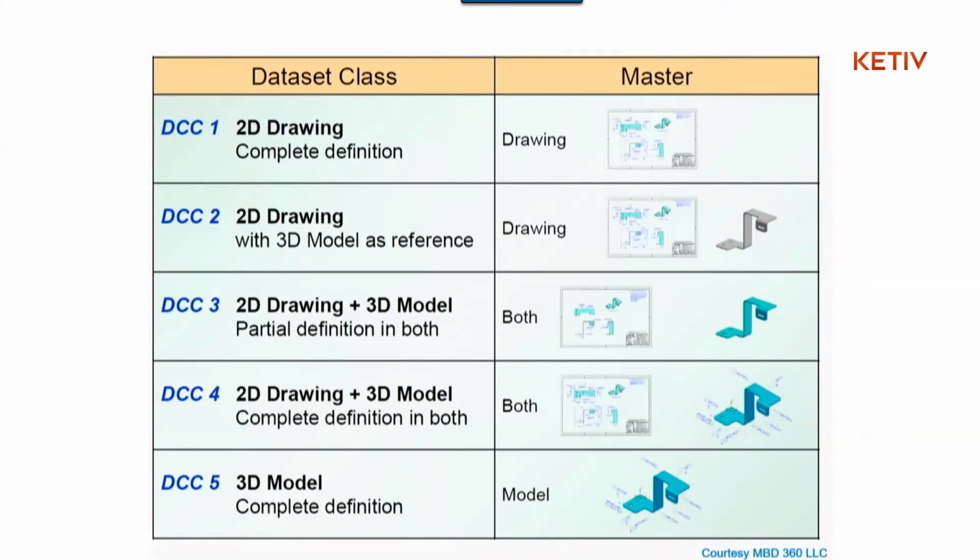So I mentioned earlier that while the ultimate goal is to eliminate the 2D drawing altogether, I don't think we're quite there yet. That is going to be the ultimate goal, but as far as the capabilities inside of Inventor, I don't believe we're quite into stage 5 here. So we are going to be more into stage 3 and stage 4, essentially having a combination of both: a model that has some of these model-based definitions, but also attached with a 2D drawing as well.